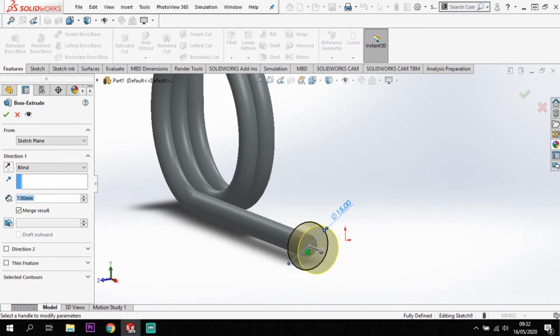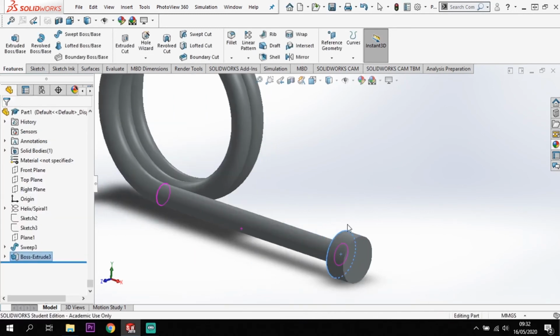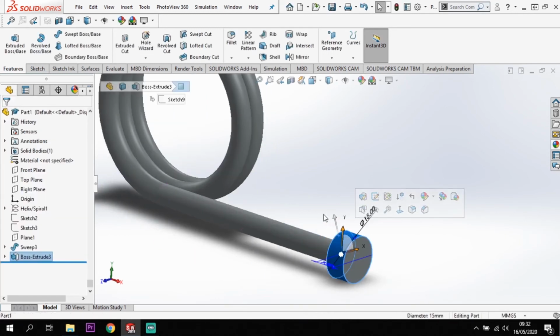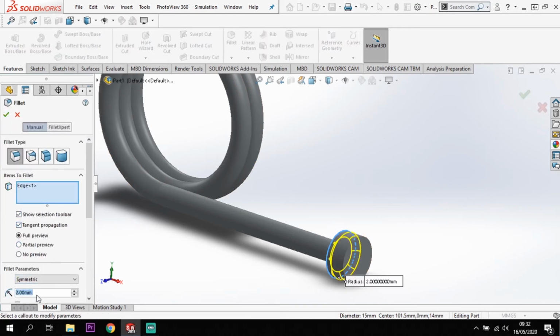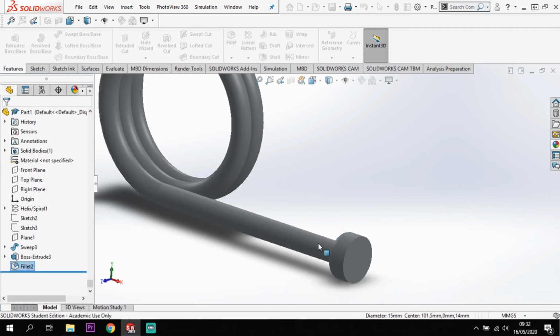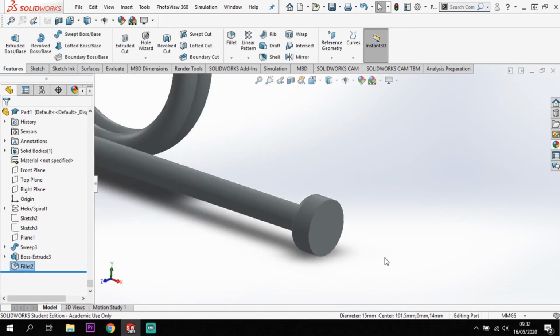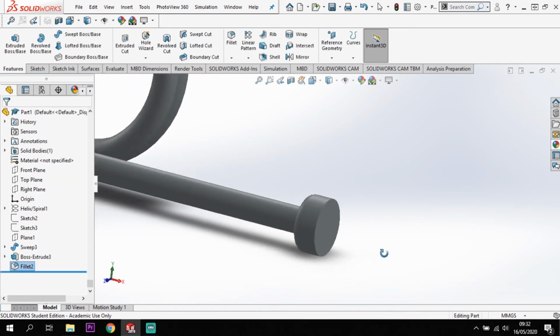And there, like so. Okay, now the inside edge, or this edge here, is going to have a fillet on it. So let's go to fillet. And that's just going to be filleted by 2 mil. So just make sure you've got 2 mils in your radius option there, and tick, and we will get that 2 mil fillet in the end there, like so.